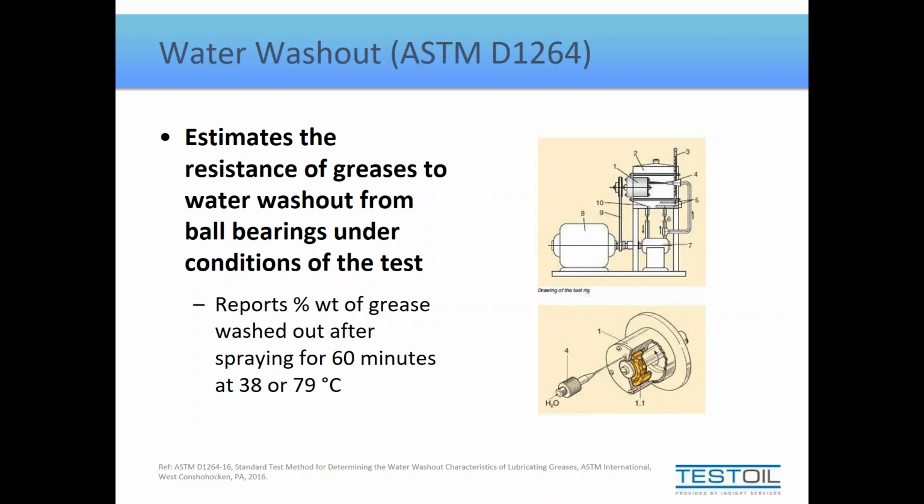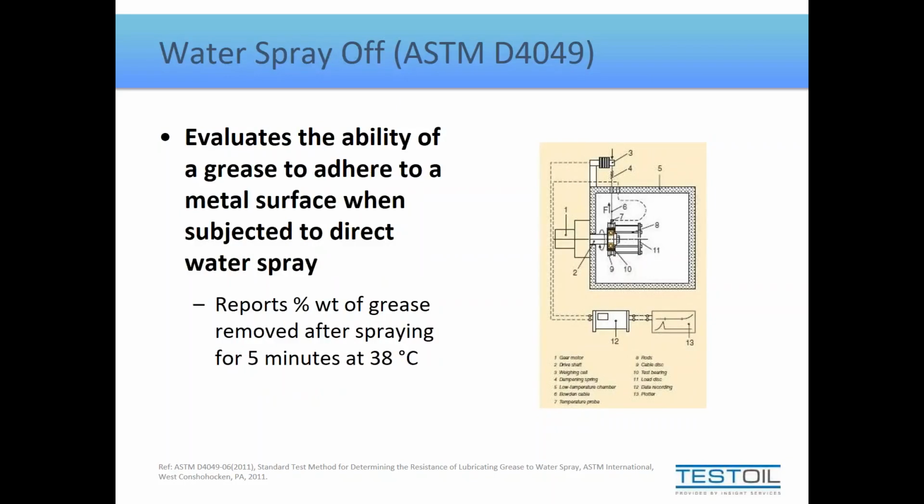If your grease application isn't necessarily a bearing, the other variant to a water test is the water spray-off test, where we just measure how much by weight, again, is sprayed off of a surface. This is a much briefer test, though. It only takes a few minutes to get the results from this one.